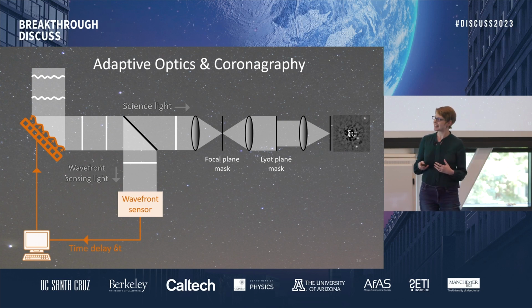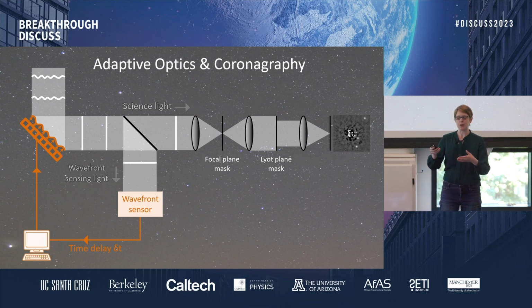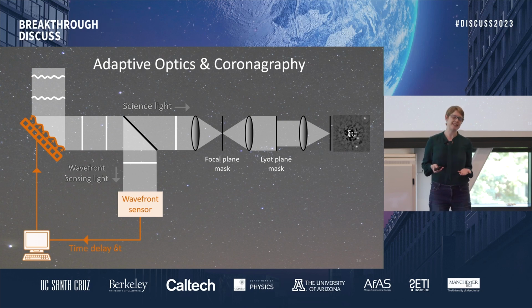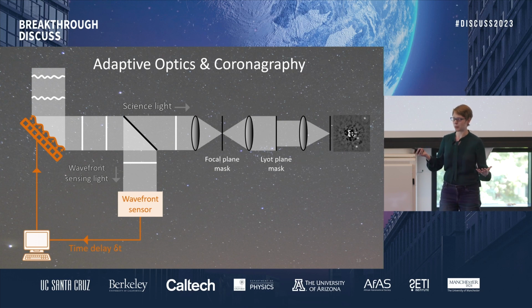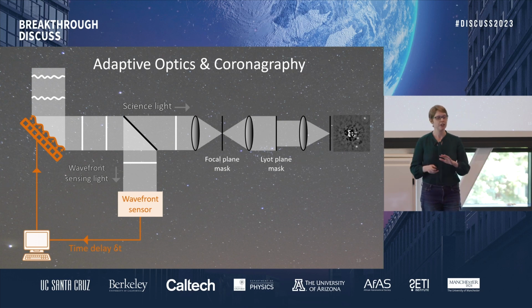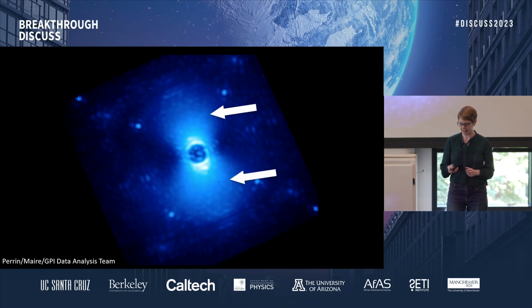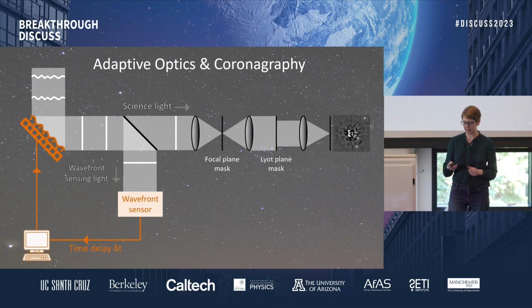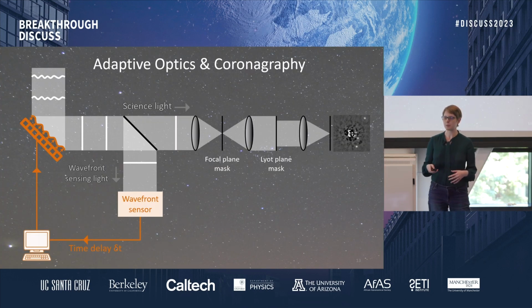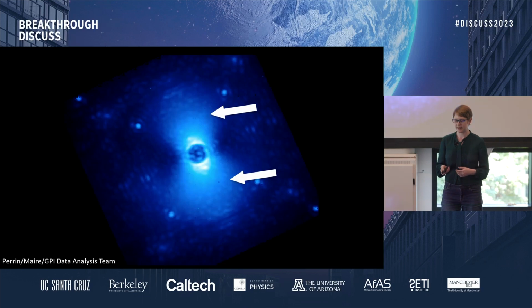Now I want to touch on a fundamental limit to the performance of an adaptive optics system, and that's its time delay. You can imagine you always have to have some exposure time on a wavefront sensing detector to collect photons from your star so that you can correctly measure the shape of the wavefront and know what shape to give the deformable mirror. So no matter what technology you use, that time delay between sensing and control is never going to be zero. I got pretty excited a couple of years ago when our colleagues Olivier Guyon and Jared Males introduced a method of predicting the wavefront, predictive wavefront control, that's just based on your previous wavefront measurements.